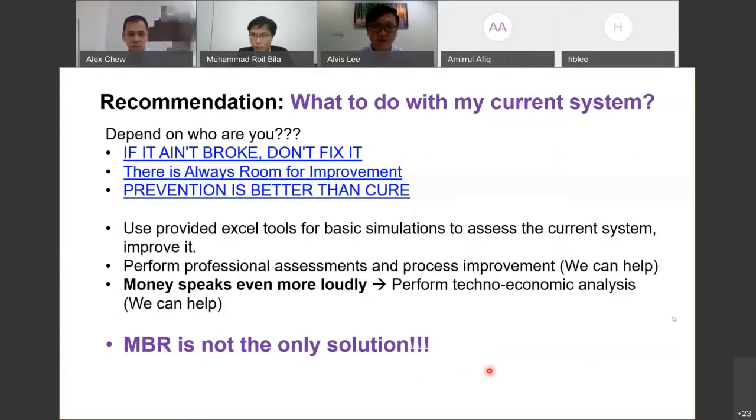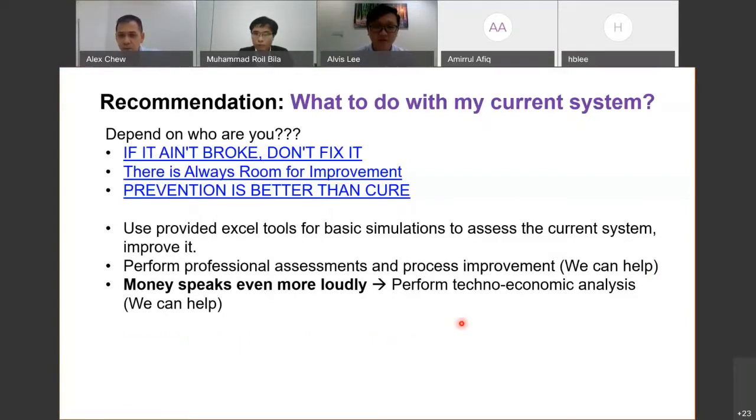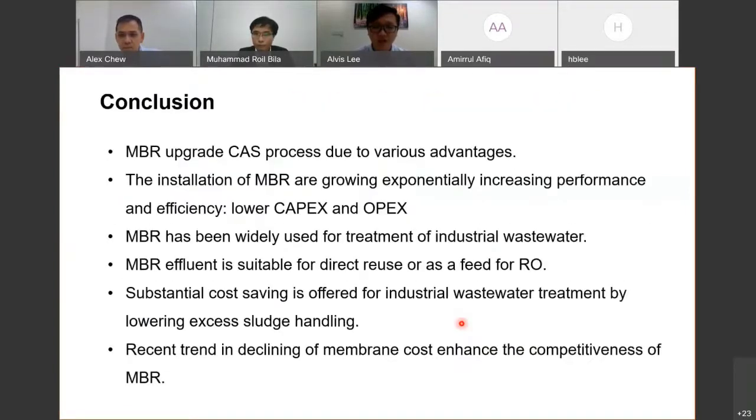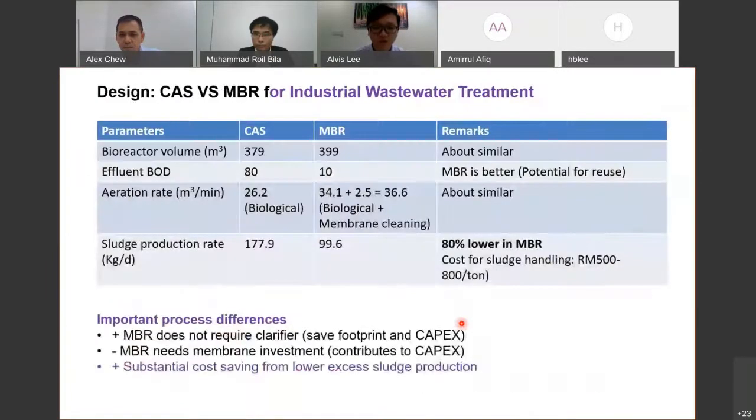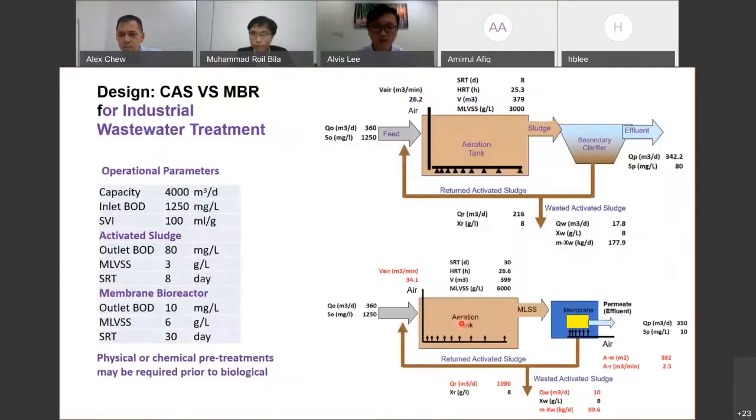So the fourth question is, membrane technology normally performs at 75% product and 25% reject. Does the MBR contain concentrate reject, or is the reject the one lost or wasted? It's the same as activated sludge. You have feed, you bring in air. If you look into the balance, you bring in the feed wastewater, you bring in the air, and you produce effluent, and you produce waste activated sludge.